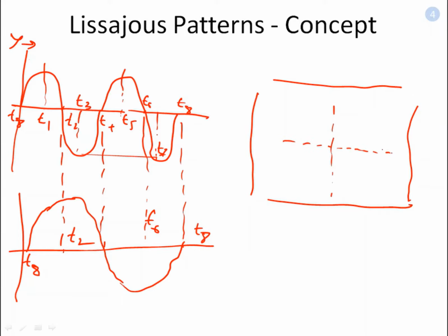So you can understand that we can adjust the origin by using the sweep signal initially if both the signals are unknown to be compared. So with the sweep signal you can find the origin and synchronize the wave. So once you have synchronized the waves, then you can give two different inputs to two different plates. Once you are giving the different inputs, how will the pattern be generated?